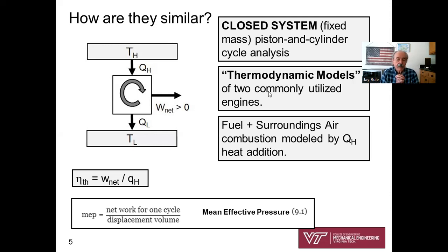The other thing that they have in common, both diesel and gasoline engines, is what's the heat source? The heat source, as you well know, is combining a hydrocarbon fuel with our surroundings air. And we do that within the piston and cylinder. That's how we get our heat source, and we're going to model the combustion process as a heat addition process.